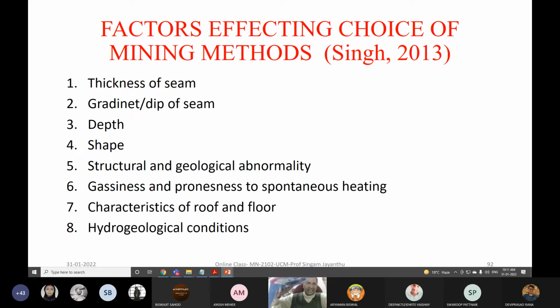Then here you can have a shaft, and it is better to have a shaft here instead of on this side. On the upper side or roof side, if you have a shaft, it will get affected by the workings. It will not get affected if it is on the deep side. Even in metal mining, the location of the shaft will be on the footwall side, this floor side. This is the way we locate it, and then with horizon mining we connect here and there from in-seam development, and this is the way they used to do it.